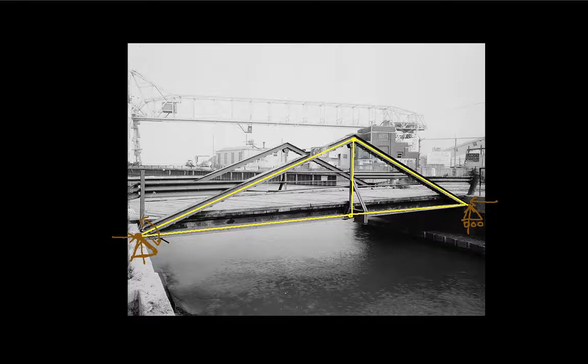And you're saying to yourself, wait, steel is not light and fluffy. But the assumption that you typically make when you're analyzing a truss, at least for the first approximation, is that the weight of the members is small relative to the weight that the truss is designed to carry. And so we will assume that these members are completely weightless, and we assume that these joints are pinned with frictionless pins. In other words, the members are free to rotate.